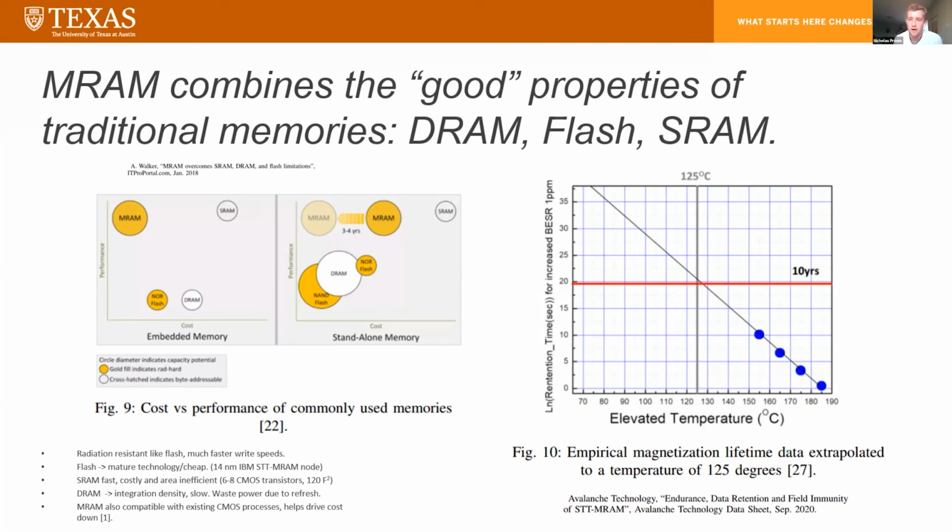So I'm not a big expert on computer architecture with MRAM, but in principle, people are looking to use MRAM for both applications, both standalone memory and to be put on a chip. It still hasn't quite hit the speeds of SRAM yet, but assuming it can achieve those, whether it's going to be used for actual random access memory on a computer depends on how the technology further develops, if that makes sense.